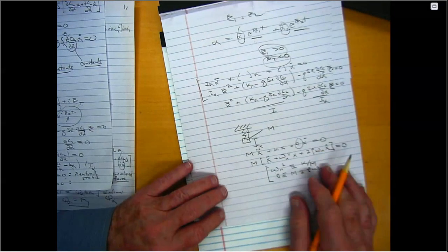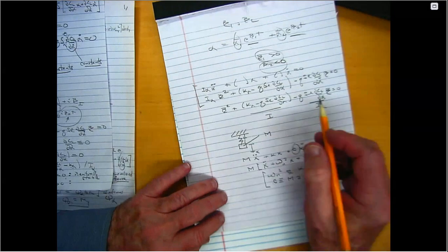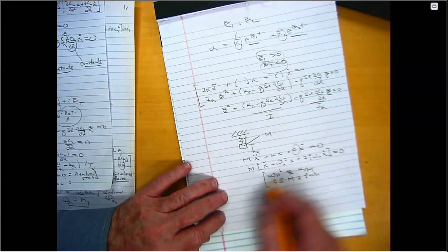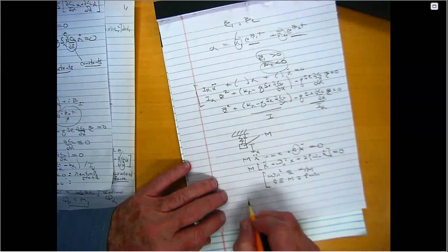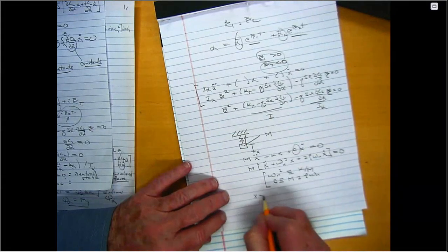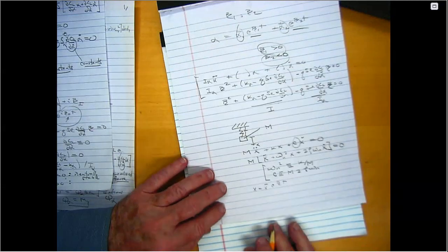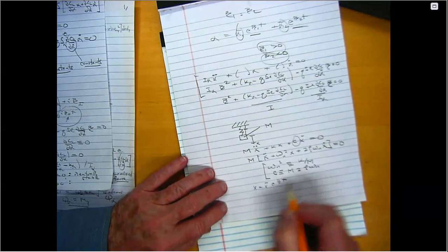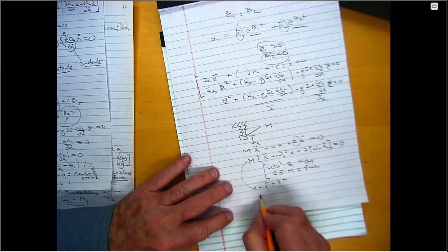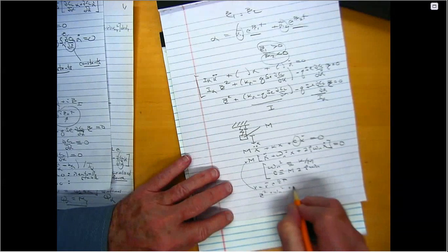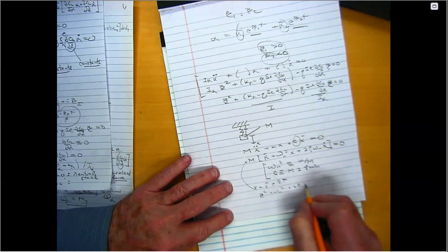And so, if I interpret, I can write down the solution for this equation by analogy to the solution for that equation. The solution for this equation is x equals x bar, again, e to the beta t, right? And now, if I substitute that into here, what are the possible values of beta? Well, there's beta squared plus omega n squared plus 2 zeta n omega n beta equals 0.